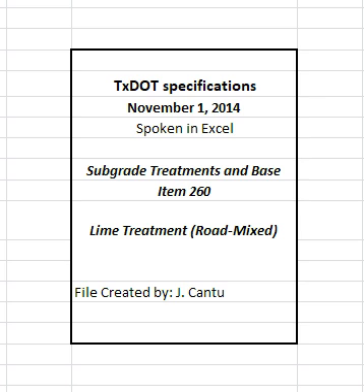4.5.2 Density control. The engineer will determine roadway density and moisture content of completed sections in accordance with TEX 115E. The engineer may accept the section if no more than one of the 5 most recent density tests is below the specified density and the failing test is no more than 3 pcf below the specified density.